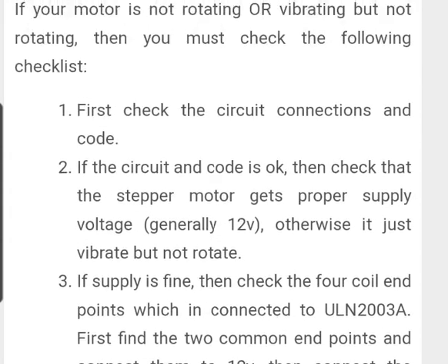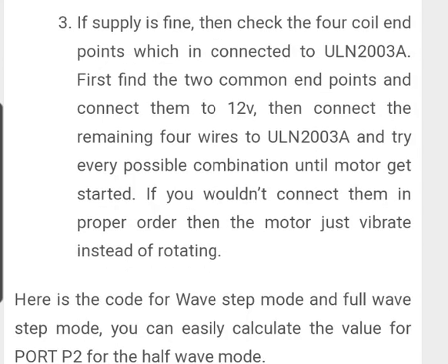So here are the steps. If the motor is only vibrating, not rotating, then we have to check all these things. The first is the circuit connection and code. If the code and circuit are okay, then we have to check whether the stepper motor gets a proper supply of 12 volt. If it is okay, then we have to check the 4 coil points which are connected to the ULN 2003A. If these connections are not proper, then the motor will just vibrate, not rotate.